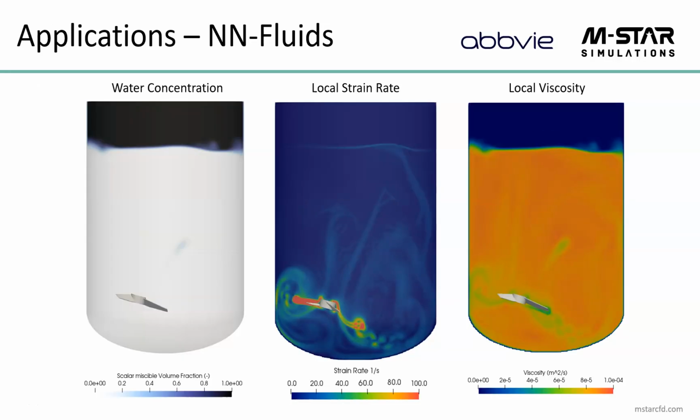Carrying on, if we're talking about more complex rheologies or APIs, active pharmaceutical ingredients, these can become expensive. Experiments can become expensive. So the more we can do these mixing studies to predict how different materials dilute, and how poorly mixed single-use mixers behave, the more we can do that in silico, the more efficiently we can do targeted experiment. Again, this isn't meant to get rid of experiment, but it does make our experiment more poignant